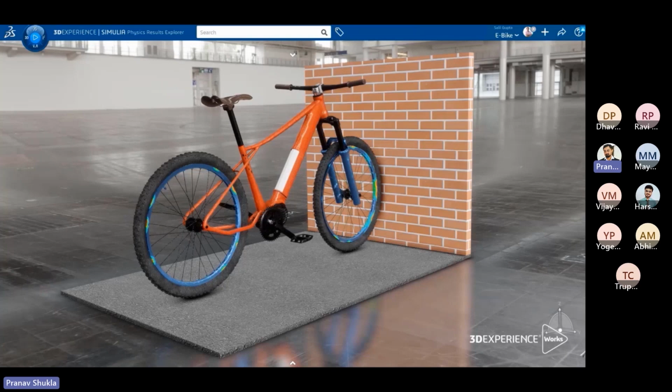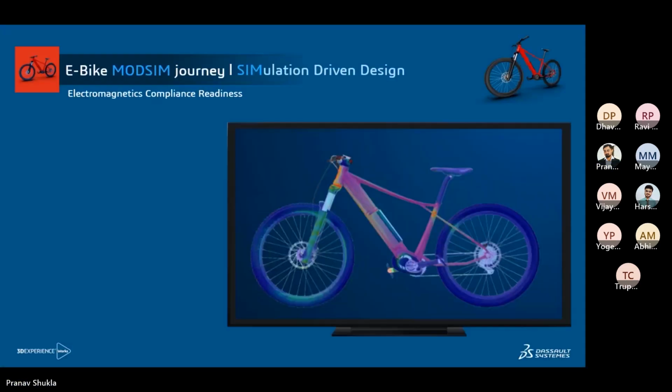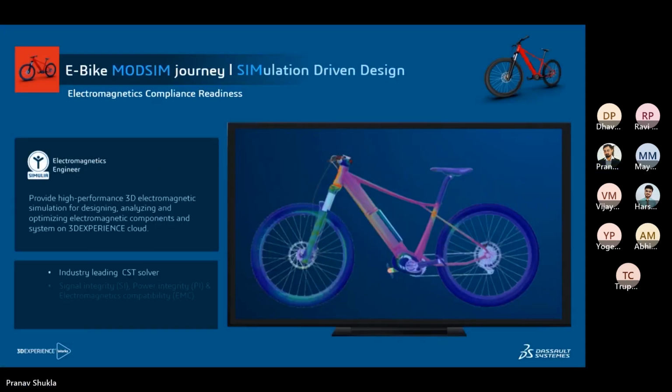Now I hope you have a look at the crash simulation. You can have an idea how the frame or the other parts will behave during the crash. This analysis has been performed using the explicit dynamics Abaqus solver. If you would like to perform crash, impact test, drop test, or bird strike with the SPH method, this explicit dynamic solver absolutely fulfills your requirement, with the additional benefits of cloud computing.